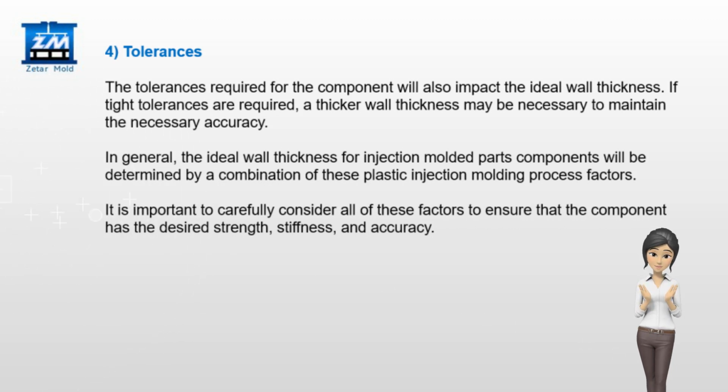Tolerances required for the component will also impact the ideal wall thickness. If tight tolerances are required, a thicker wall thickness may be necessary to maintain the necessary accuracy.